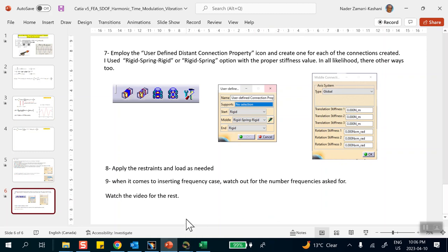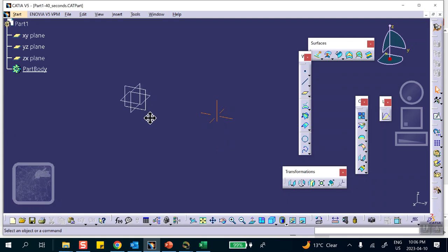I already did this in video 1, but people may say, why are you creating beam elements if you're not going to be using them? Well, unfortunately, if you don't do it, then you can't define the spring element either. Now, there are other packages that allow you to define discrete elements such as dampers and springs and things like that, but not here.